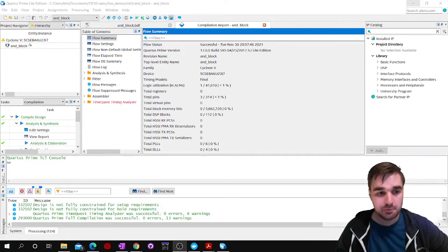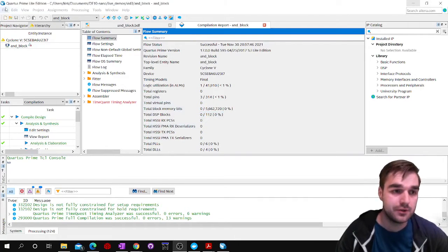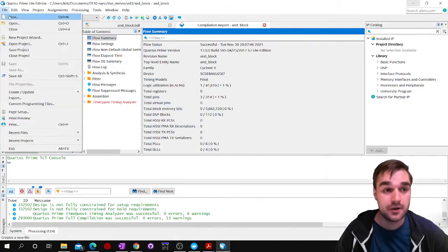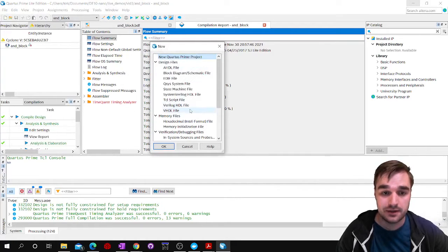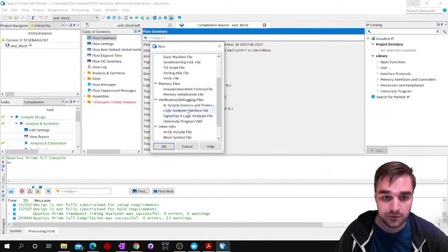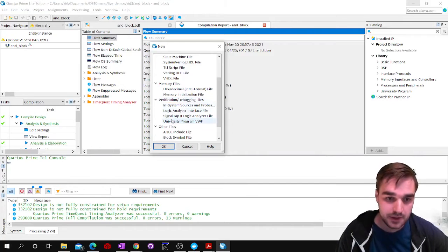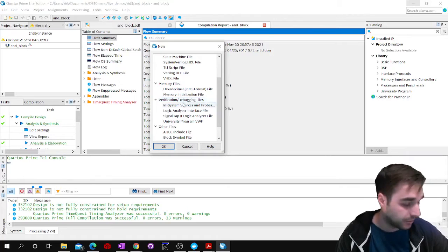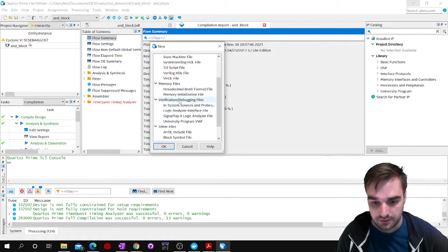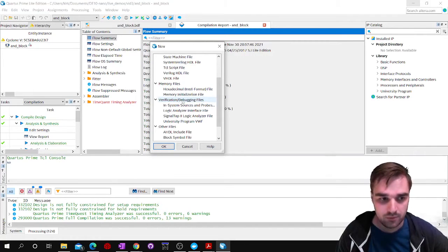Okay, welcome back. So at this point, we are ready to program the board, but one little detour I wanted to make, and I just wanted to show this to you. This is really fast. I'm going to go to File, New. I'm going to add a new file to this project, and I'm going to add the one that is called, if you scroll down, under Verification Debugging. This is sort of a debugging step before you actually load it onto your board. This is a better way of making sure your circuits work before you bother putting it on your board. And it's basically going to let you find where your code is going wrong or whatever it might be.